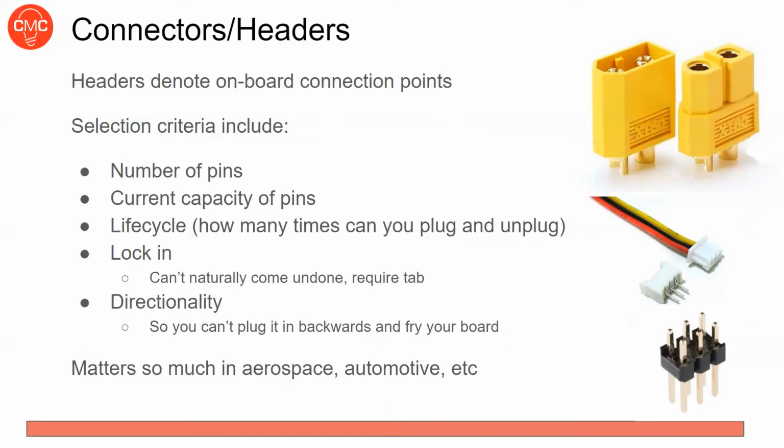You might also want to consider the life cycle. So are you going to continuously plug and unplug this thing, or are you just going to plug it in once and leave it there, and only unplug it if you need to test something? Your life cycle matters, whether it's 10 cycles or 10,000 cycles. Some connectors have lock-in capability, so you need to push in a tab or something to unplug it, and that's really great if you don't want it to accidentally come unconnected if it's being pulled on for some kind of strain in the circuit.